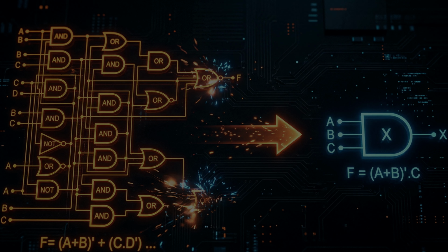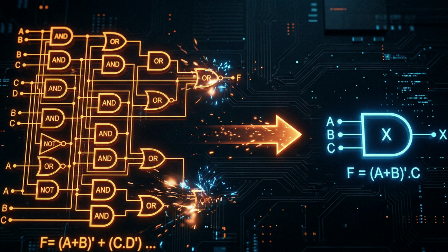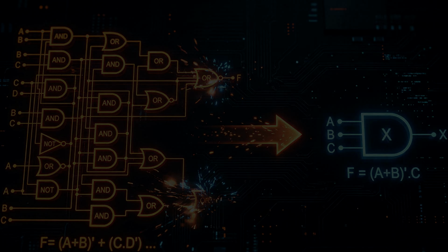Second stage, the optimization. At this stage, the synthesizer simplifies your logic expressions and removes unnecessary gates. It seeks ways to produce the same result with fewer transistors. A and A or B is simply equal to A. Of course, the synthesizer knows this and deletes the unnecessary gate. This stage is technology independent. There is nothing FPGA specific yet. You can see only pure mathematics.